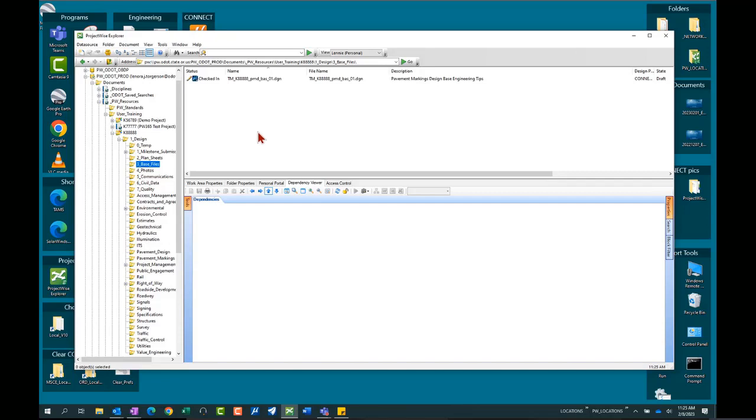Unless there are questions, let's take a look at creating a MicroStation terrain. The reason you might want a MicroStation terrain is maybe you want the ability to display contours. And you might want to display contours differently than anybody else in the world. You might want to change your interval, for example. So let's create that kind of a base file.